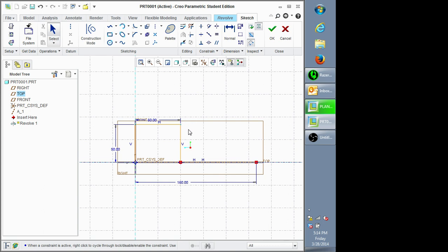And there you go. Now, if you had it as a free-floating edge, it could potentially get messed up. When I'm sketching, I like to have an edge right here controlling it. So this is pretty much saying that it won't mess up. It'll still stay there, but you want to delete it before you finalize your sketch.